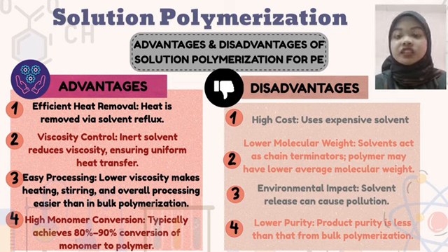Next, disadvantages of solution polymerization. Firstly, high cost. The use of expensive solvent increases overall production costs. Secondly, lower molecular weight. Solvent can act as a chain terminator, resulting in polymer with lower average molecular weight.